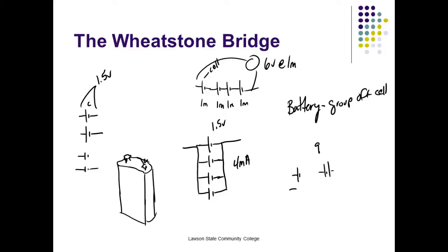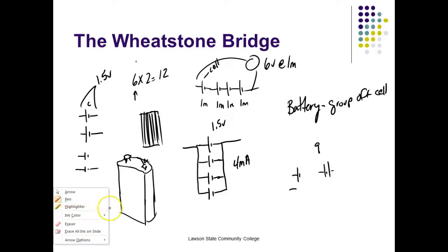Your car is a battery. Your car has 6 cells. It's lead acid, so 6 cells gives us about 2 volts per cell. So that's 12 volts. And now they've got a bunch of cells in parallel. When we say 6 cells, each cell has tons of cells. If you ever looked down inside a battery, you'll see they're in groups of plates. They're hooking them in parallel there, and then you have each group isolated from each other, and that would be the 6 different cells. So that's why you get 12 volts out of the battery.